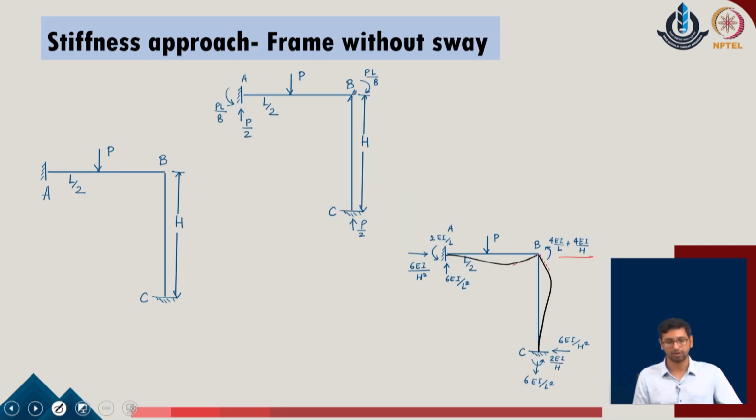Once we do this calculation, we realize that this is what we initially generate. This is our loading system, or the fixed end system, and this is our system which corresponds to the unit rotation released at joint B of the given problem. And once we generate these values, we understand that P equal to PL plus KS delta can be defined.